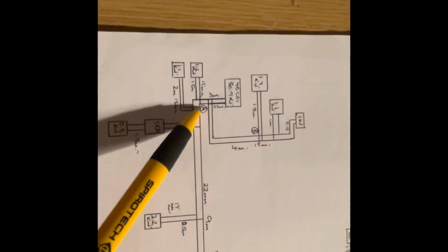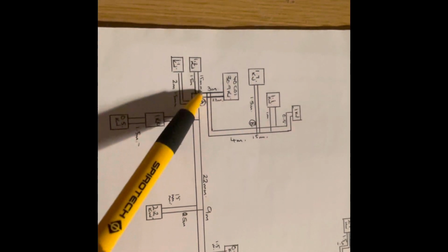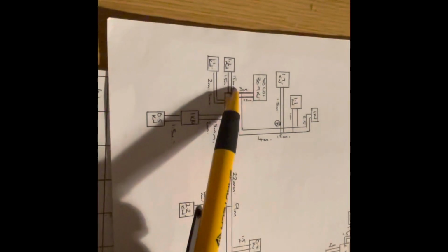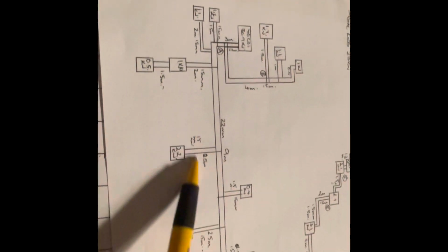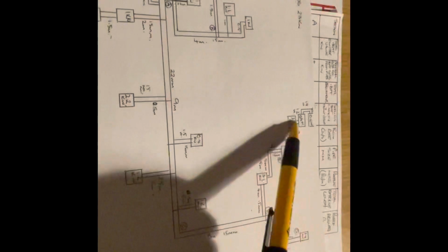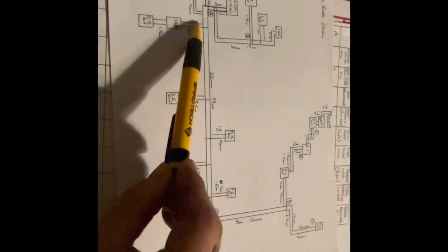So therefore I created some close couple T's below the boiler. Same again as I did with this one. The pump looks after my primary loop, and then my secondary pump fed this zone, and I ran another flow to feed this zone around here, and another return coming back, I think, joined in, and then these work perfect. Ten other installers had been to this job before me and couldn't resolve the issue, and this was the first time I used close couple T's. That was 6-7 years ago, and they've got me out of trouble so many times.